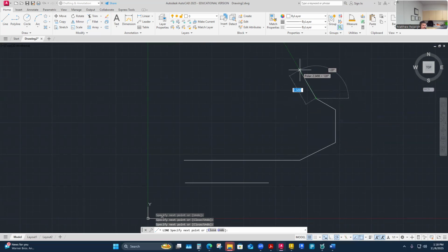How you get that turned off is you can always hit escape. Enter also works when you're in a command like this. Enter kind of works as escape, which is kind of weird, but that's the way it is. It's like you finish drawing. I probably use enter a lot just because my hand is over on the 10 key pad where I'm putting in numbers, and there's an enter button right there. So I tend to use enter to escape commands a lot.